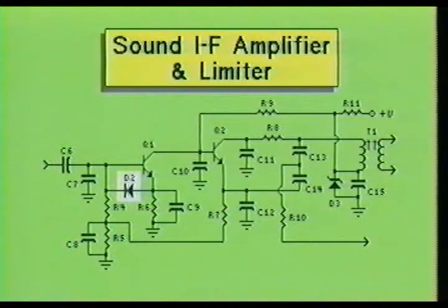Diode D2 bridges across the emitter and base of transistor Q1. Diode D2 clamps the 4.5 MHz IF signal level going into the base. For this reason, the current across D2 is at times quite high. This diode serves to clip each negative half cycle of the input signal. Resistor R6 and capacitor C9 work together to regulate what transistor Q1's emitter sees. Resistor R6 provides the DC path, while capacitor C9 couples any AC signals to ground.